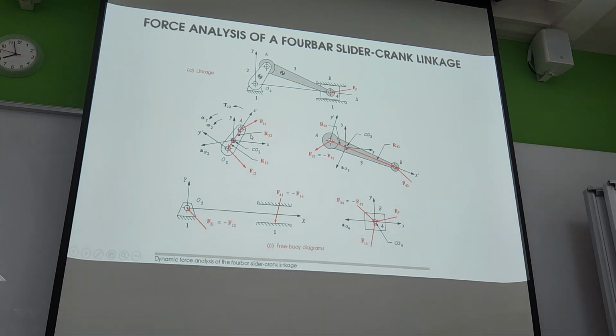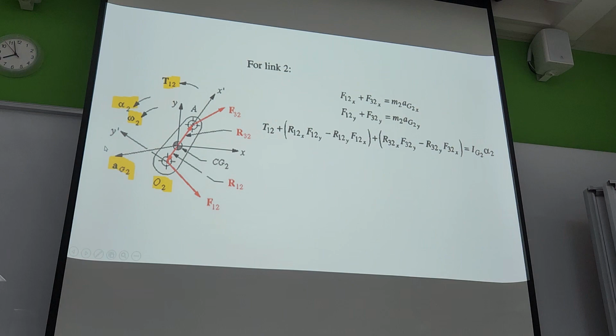Focus here. I'll go back to the next slide. Now you can see here. Okay. So this is approximately how you draw link 2. Identify the centroid. It's up to you, just locate the centroid. Now from the centroid, this link is connected to link 3 here, and to the ground here, right? So now the position of 1 from 2 is directed downwards. So the position vector is downwards. Now the force acting on 1 and 2, whether you show it like this or like this, doesn't matter.